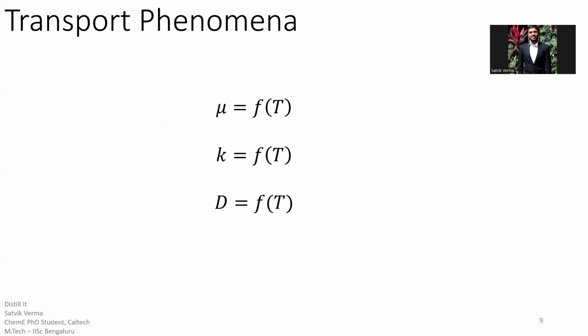Similarly, you can apply this to transport phenomena while you are trying to figure out a dependence of terms such as viscosity, thermal conductivity, diffusion coefficient. If you see, these all are functions of temperature, right? So you can get mu versus temperature data, K versus temperature data, D versus temperature data, and you can try to fit it to a non-linear equation.